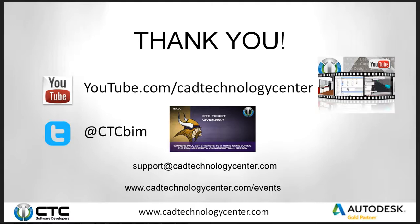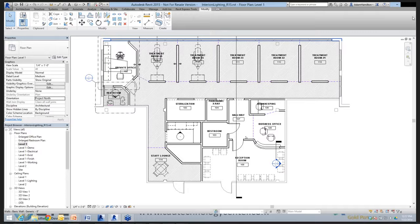And Adam, our first question here is, what if I'm working with linked models? The underlay option is not always available with linked models. Sure, and yep, that's an important part. When there is an issue with underlay options in linked models, sometimes what I would do is modify the view range of the ceiling plan to be dropped down to a floor plan level, or if there's a specific area you want to work, we talked about the plan regions.